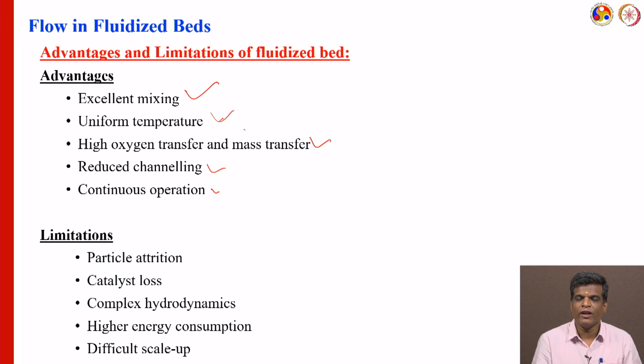When you use any packed bed or fluidized bed, there are limitations. So what are the limitations of the fluidized bed? Particle attrition, and definitely catalyst loss. Sometimes when you increase the velocity, the catalyst will go outside. Then the hydrodynamics are definitely complex: there is gas, liquid, and solid, all with transfer taking place, so it is very complex to understand. We also need higher energy consumption compared to the packed bed. And the scale up is difficult; you have to look very carefully to scale up the process.